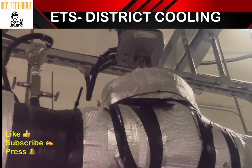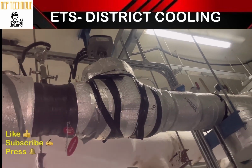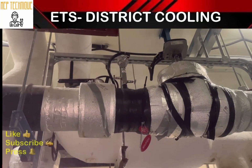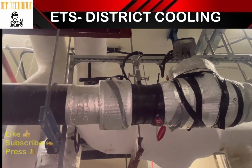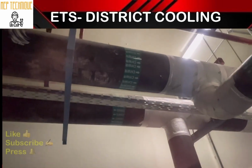PICV means pressure independent control valve, to balance the chilled water line. Again there is a differential pressure switch you can see here, and the differential pressure transmitter DPT. Then again a butterfly valve, and it is connected with the main line of the distribution company.